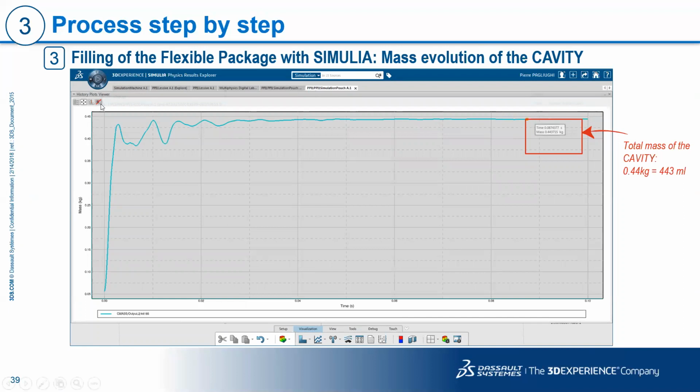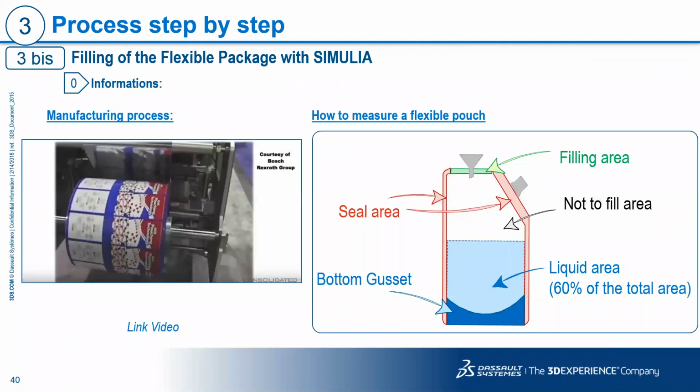So basically, this is the addition of mass. You can look into the XY plot here. As we progressed in time, with time on the x-axis and mass on the y-axis, we added mass to it, and essentially once the mass reached some stable state, the simulation stabilized there. The total mass of the cavity we can query for, and so we know how much we have put in.